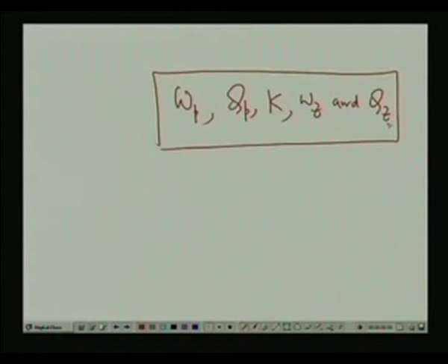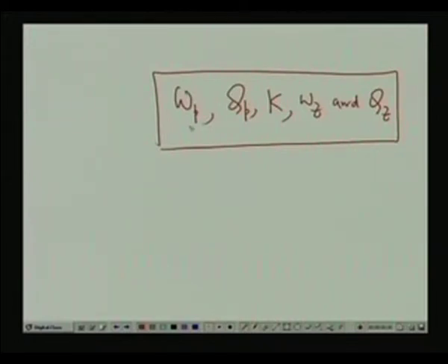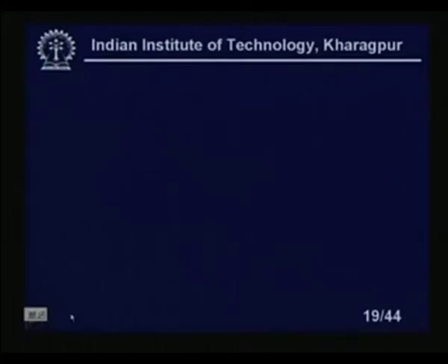Now, how can I make orthogonal tuning? It means that if I use some resistance to tune, or some capacitance, I will consider the resistance. Suppose I want to change or modify or tune this omega p. By changing some resistance, if I tune omega p, the other filter parameters should remain intact. That is called the orthogonal tuning. Okay. Now, if you go back, you see here,